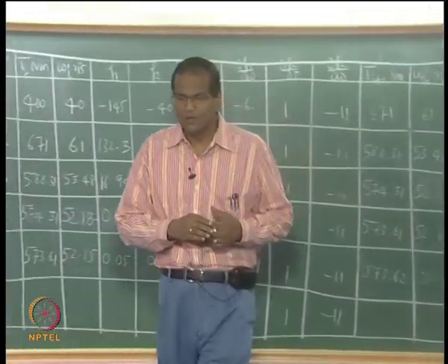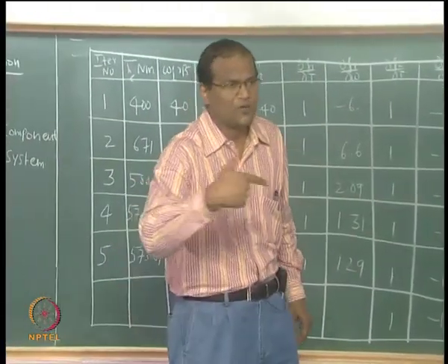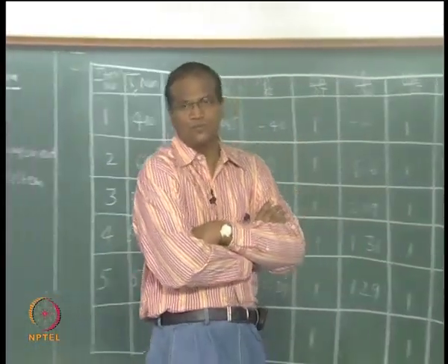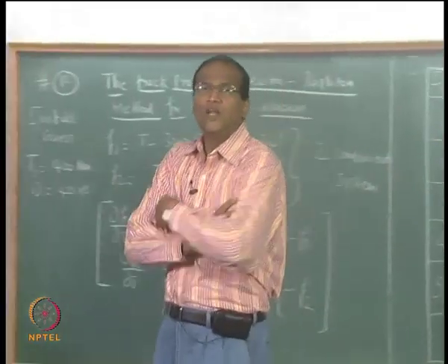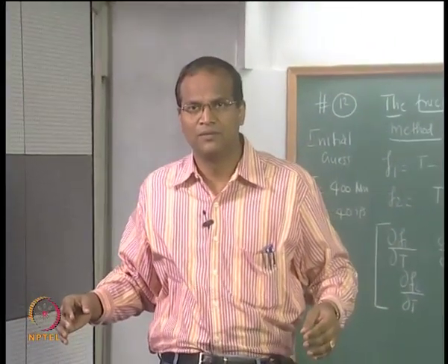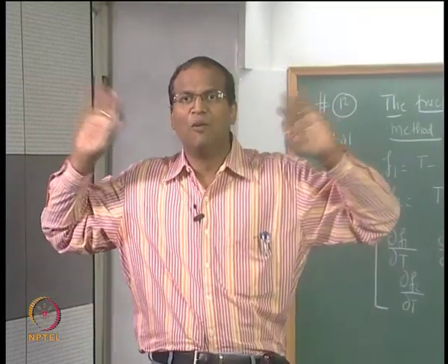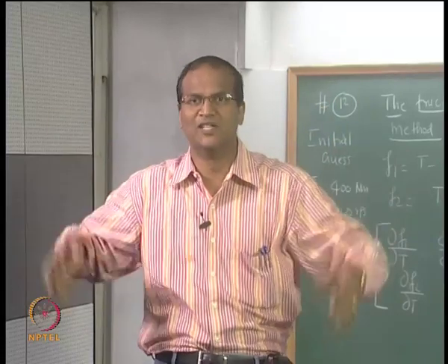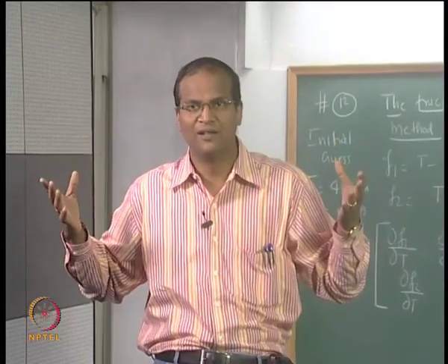For example, when you use Fluent and solve a system of equations, Navier-Stokes equation, energy equation, you can beautifully converge to a totally wrong answer. That is, your momentum equation 10 to the power of minus something, continuity equation 10 to the power of minus 4 residuals, energy 10 to the power of minus 8.